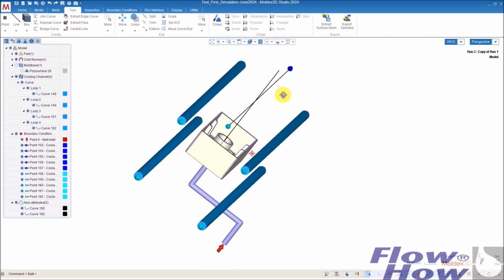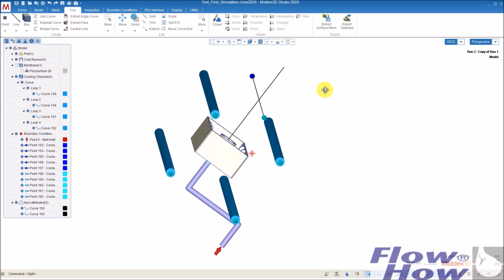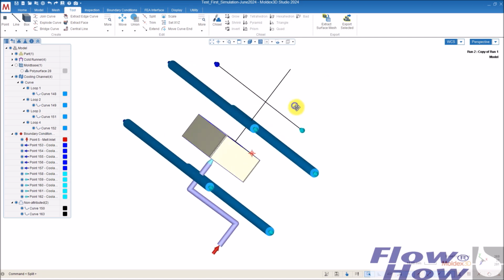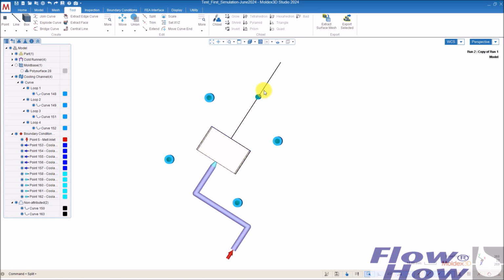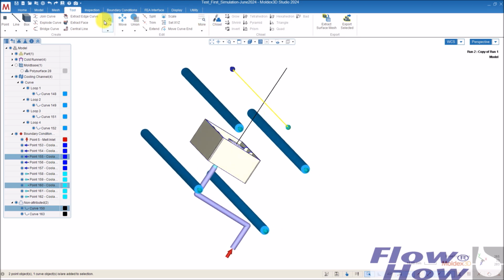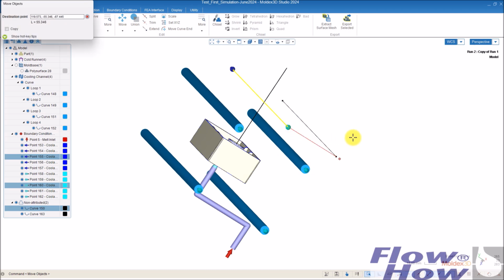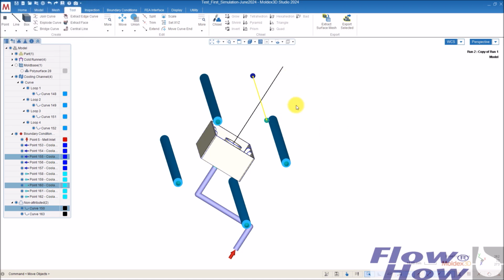So now I think they are not totally aligned. So what I can do is I can mark these three things, and I can say move here, and then I can take a direction by hitting tabulator. I lock the direction, I can't go anywhere else, and then I can use this as a reference, like this.